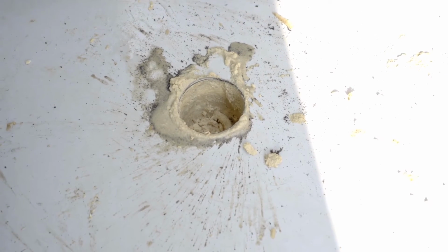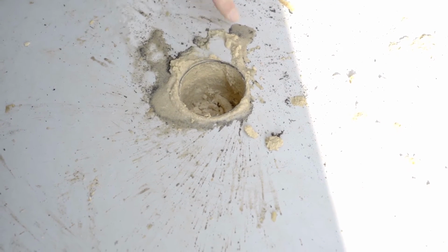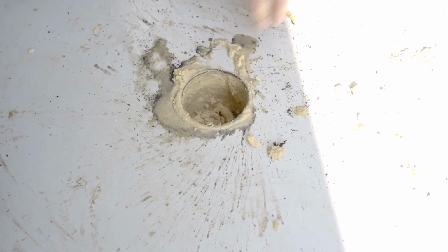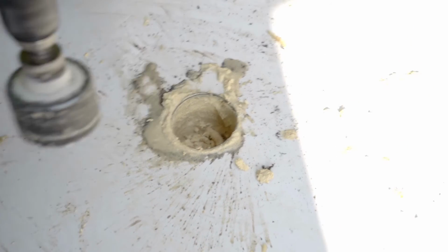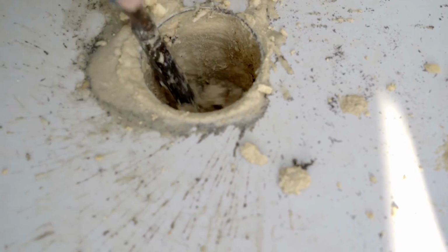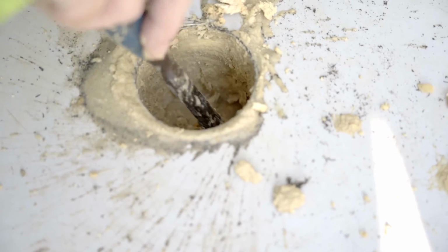It's completely saturated right down to the core, holding gallons of water. So that tells me that I need to take up the insulation, get down to the deck and dry it out and put a new system on. The hole I've just done is now filling up with water. It's pretty much like digging holes in sand, this.